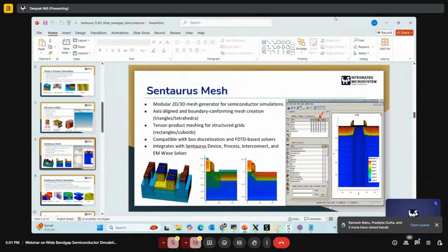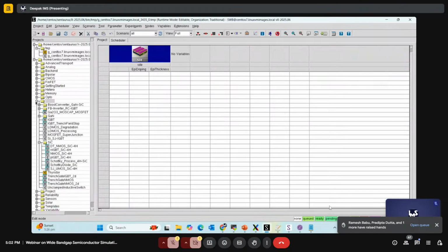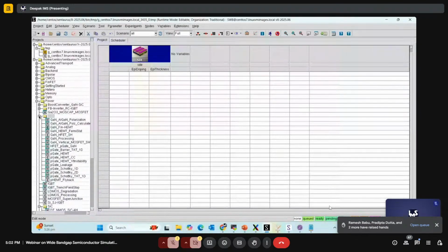The next question is regarding GaN or high power devices. A lot of issues are there, sir, regarding errors in CV characteristics. So when the device does not converge in terms of CV characteristics, what parameters is it required to vary or change to get the device to converge?